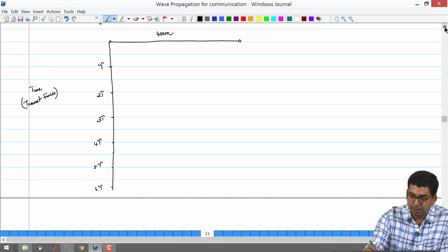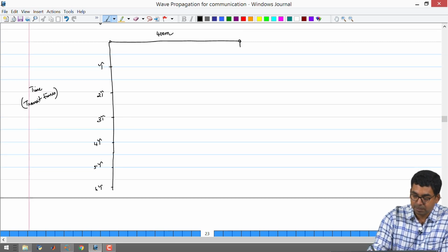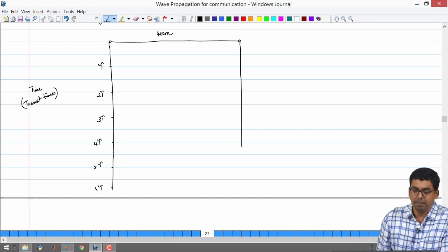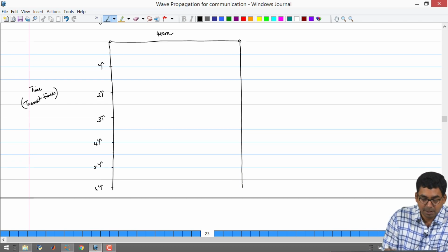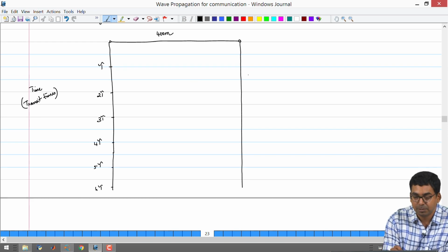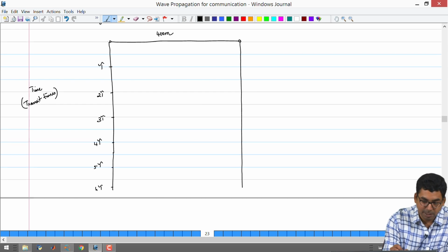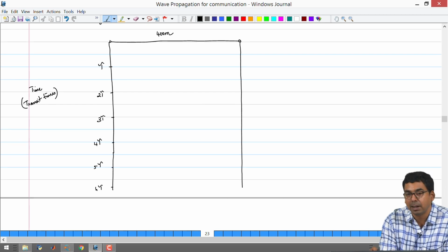On the other side also you will have an axis, it is going to denote your transit time, and the way we do this is we just make arrow plots going from one side to the other side. In one transit time, the voltage on the left hand side, where you are going to be launching some 30 volts, will reach the other side of the transmission line.